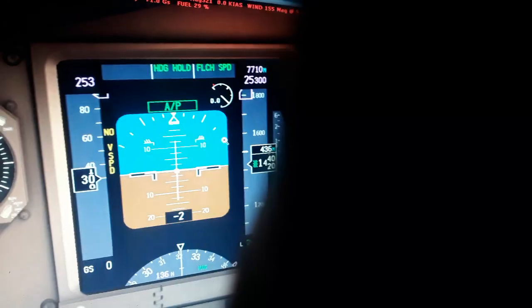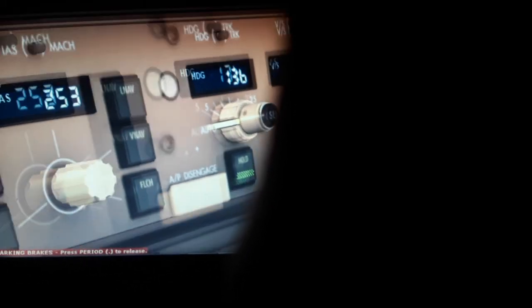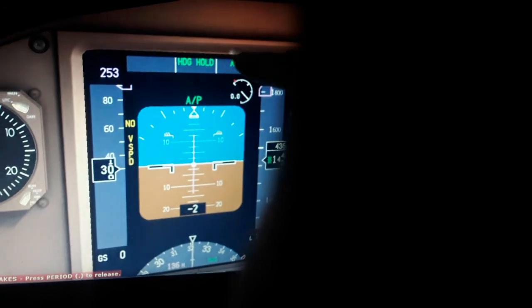You will see all this information again with the autopilot on. Flight level change. We can set also the altitude hold over here. So one mode overlaps the other and cancels it. So we can use only altitude or flight level change speed for the climb mode.